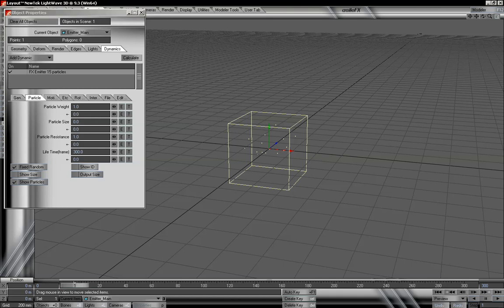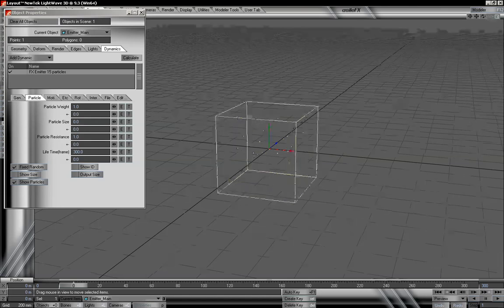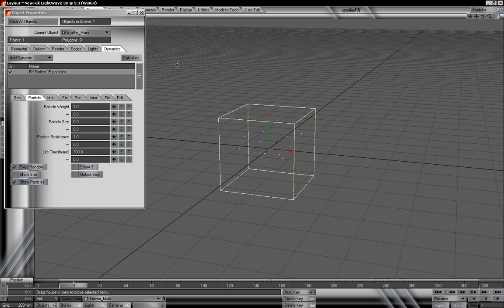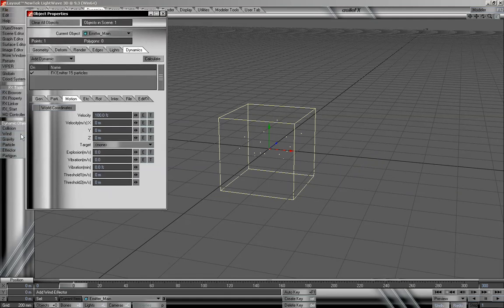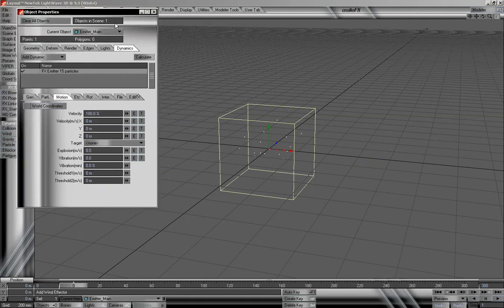And this is just a very good length for a very quick animation, and if we need to, we can always expand upon that a little bit further. The motion for these particles I'm going to create within the emitter itself and not use any global settings for gravity by using gravity objects or wind objects, because I want to do pretty much everything within the emitter itself.